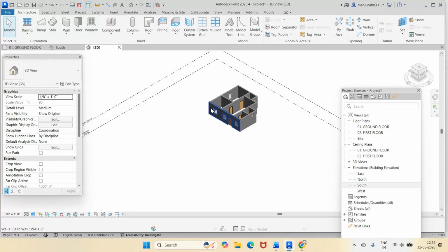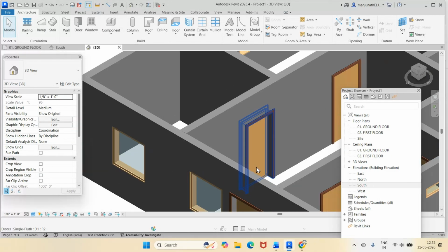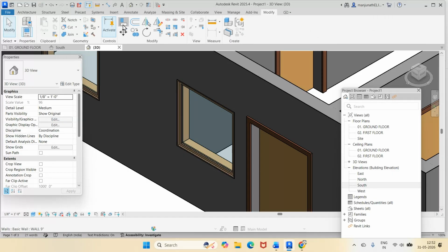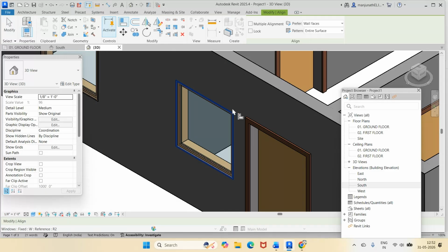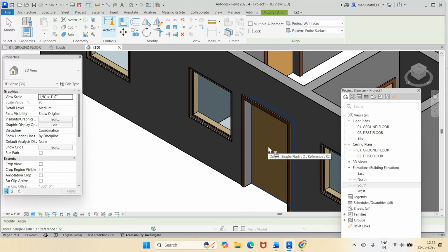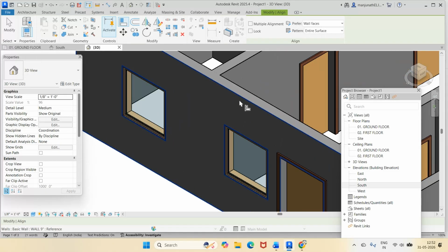So what I want is I want all the windows and doors to be the same height. So here I will just come down to this. I'll try to check whether it is there or not. So I'll go for the modify and go to alignment. Select this door with reference to this one. So that will move out. Just go down to, what is that? Where is that? Yeah, it's inside. Yes. Now I want to go for alignment. Just click on this face. Okay, onto this face.